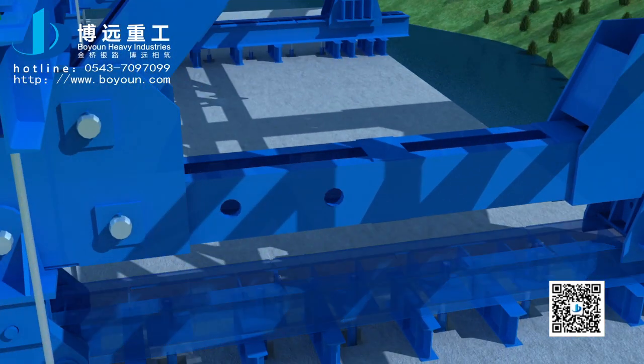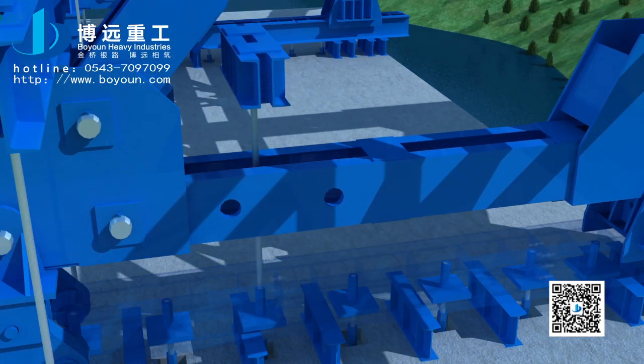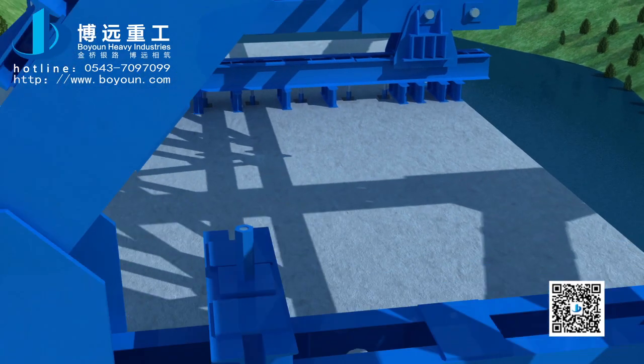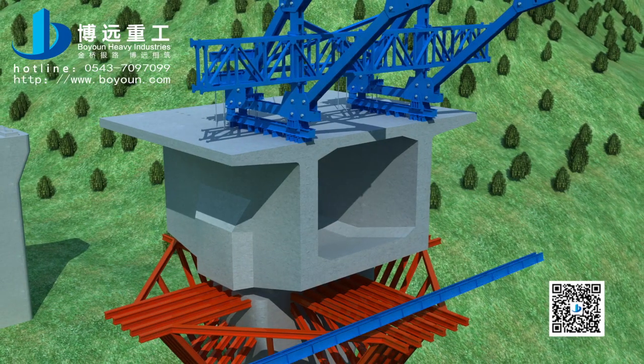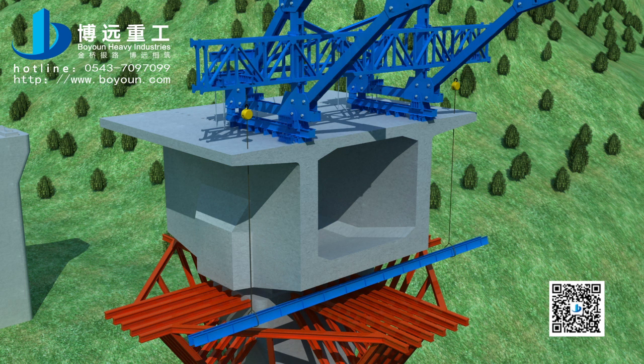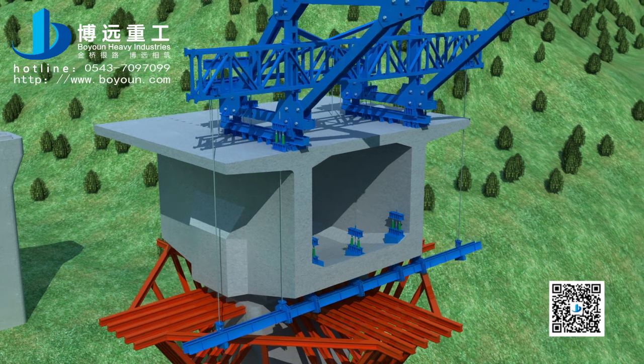The lower cord of the diamond frame is set with a bolting girder to increase the security of the cantilever forming traveler against overturning. Install the rear joist through the bottom formwork reserved hole, and hang the rear joist in place by hangover rod and hangover frame at top and bottom to connect and fix.